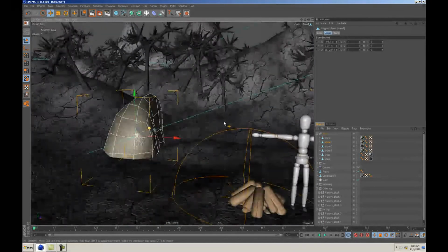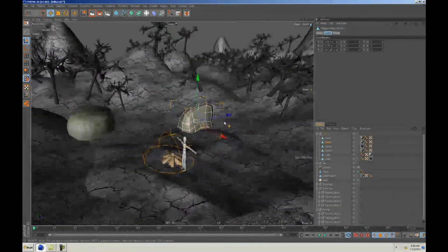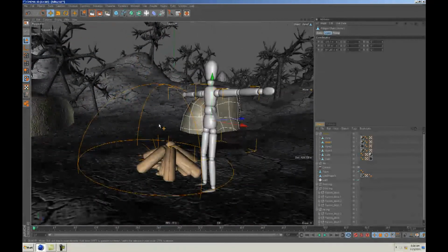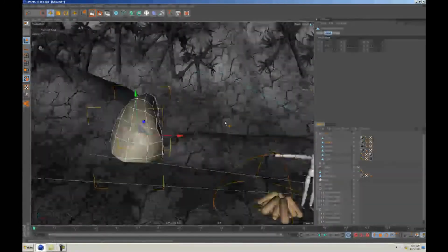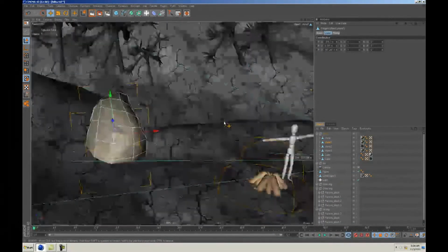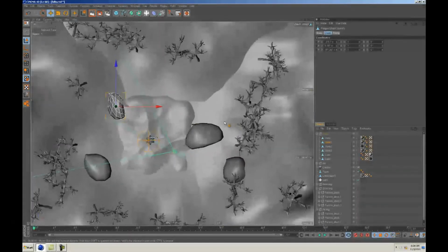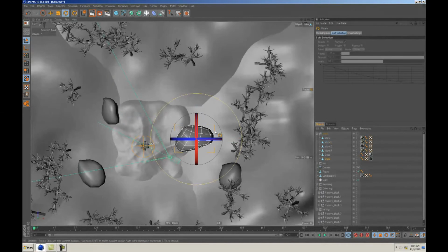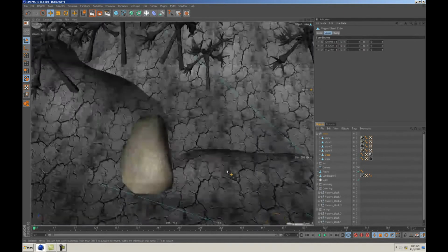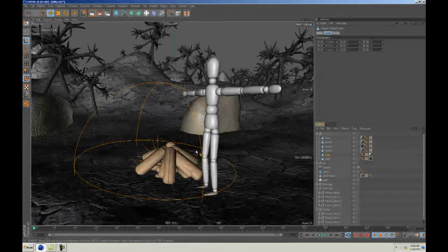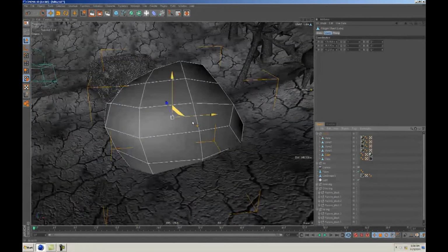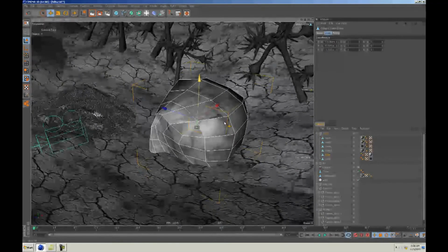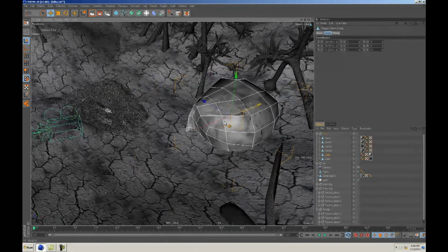So this is usually the way I work. I'll have my main camera view, which is the camera that's going to frame the shot. Then I usually have the top view, and then I have another perspective view that's kind of free. And then this one's usually a straight side view like that. So we can go into the top. This rock, we'll rotate it. This one, is that where we want it? I use this one so it stays in place and frames the shot. This perspective I use so I can click on the object and press O and frame it, so then I can go to where it is. Because if you do that with your main camera, then it's jumping, it's messing up your framing.